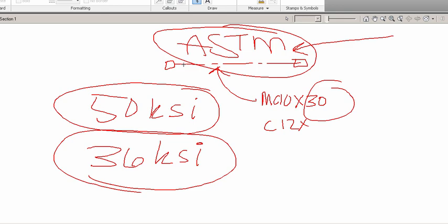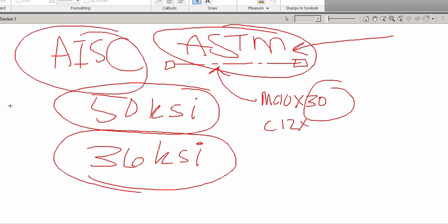And another group that you can check out is AISC, and you can Google these terms for yourself. These are institutes and groups that basically create standards. I actually have some AISC manuals that I use for my structural design, simply because they have nice graphics and those kinds of things. If you get into steel fabrication, you might be using manuals provided by AISC, but you're going to be buying steel that meets ASTM standards. Okay? Hopefully that makes some sense.